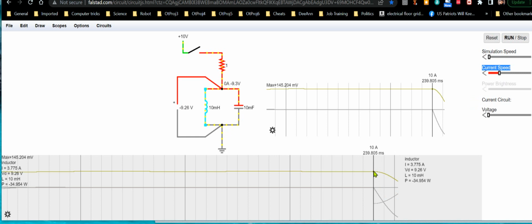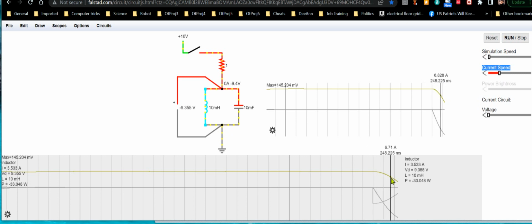An inductor is just the opposite. Here we're starting out in a state where it has a current flowing through it, and by default it doesn't want that current to change, but it has 0 voltage across it. Now that we've thrown the switch, it's becoming the source, so it's losing its energy to charge up the capacitor, because it's trying to do whatever it can to maintain that 10 amp current through it.